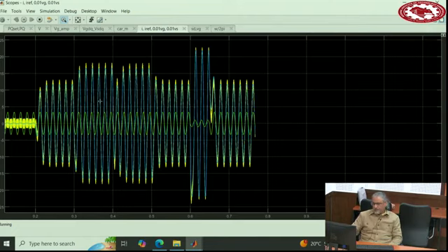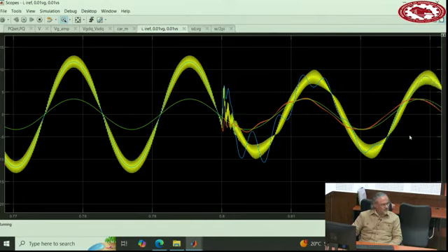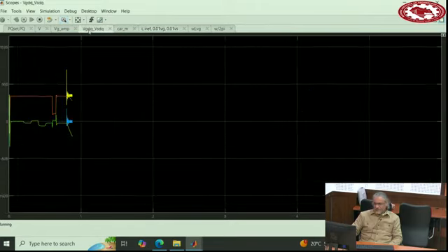I think here is when it's disconnected from the grid at 0.8, I believe. Yeah, it was a little transient. See, it's a transient because you disconnected from the grid. And you can see it here. Now VSD and VSQ start going off.